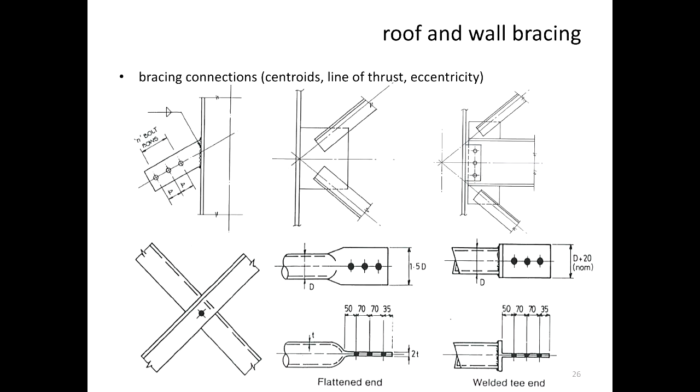If you're using a circular bar, for example, circular bars are usually difficult to join, which I explained, I think, 2 weeks ago or last week, I can't remember. So normally, if you're using a circular bar, there are different ways in which you can join them. So normally when you are providing the connections, you can have a welded connection with a cleat plate, and then you have bolts, or you can have a cleat plate like that, and then you have that welded at times. So you can have different layouts like that, and that all just depends.